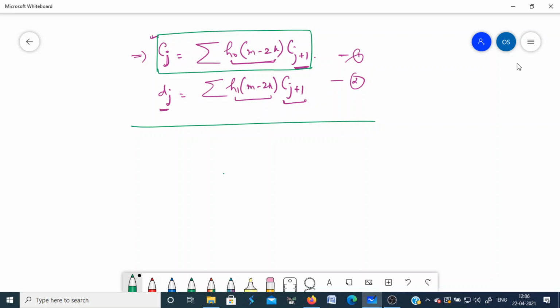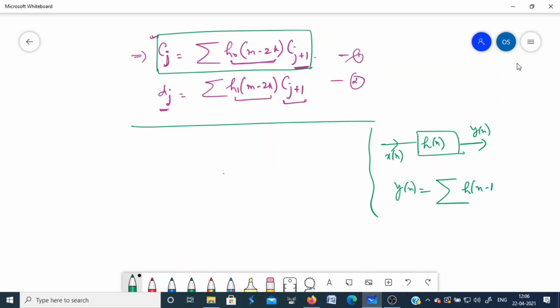Okay, if you see the equation of convolution in discrete time filters, you have a signal x[n] passing through a filter with some impulse response h[n]. So you get output sequence y[n], where y[n] is the convolution between x and h. That is, it is h of n minus k into x of k, summation over k. So you basically fold one sequence and you shift it, multiply with the other, add, and so on. You get y0, then y1, y2, and so on.